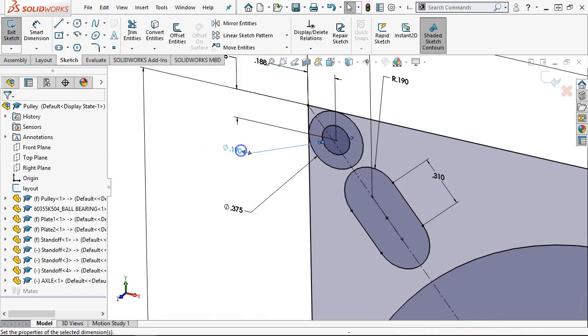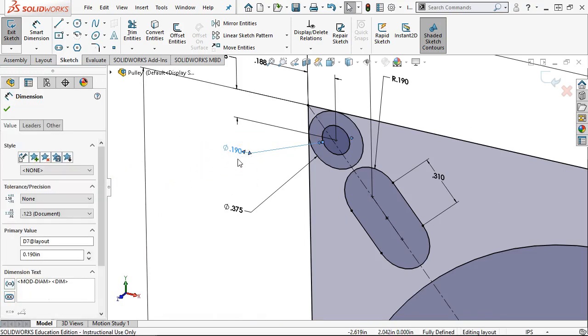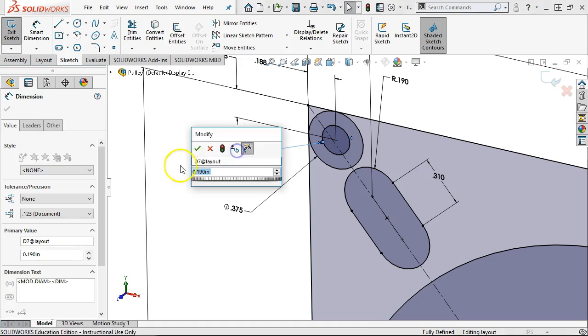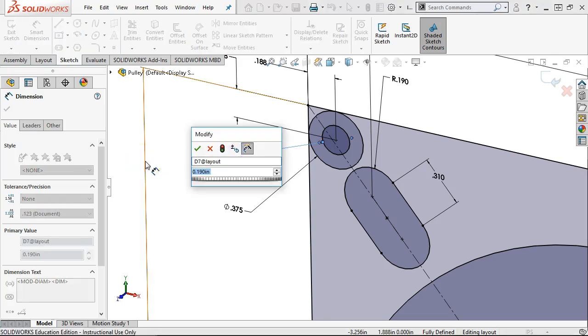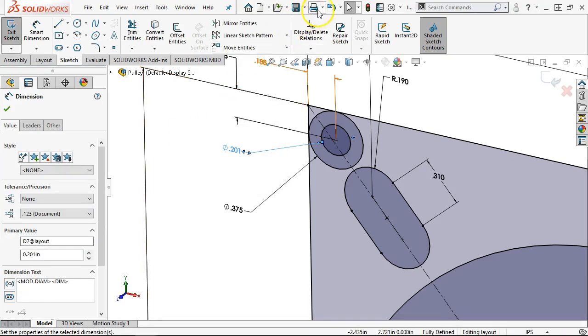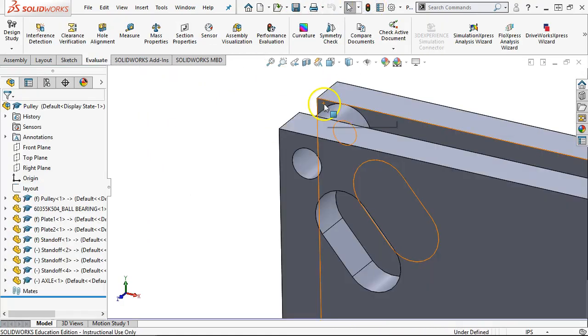All right, so looking at this, the 0.19, when our threaded hole is about 0.187 to 0.185, is still going to be pretty tight. So when we're looking at this from a positional standpoint, a standard clearance is going to probably be 0.201, number 7 drill. So I'm going to bump that up to 0.201 so that we can start looking at the positional tolerance.